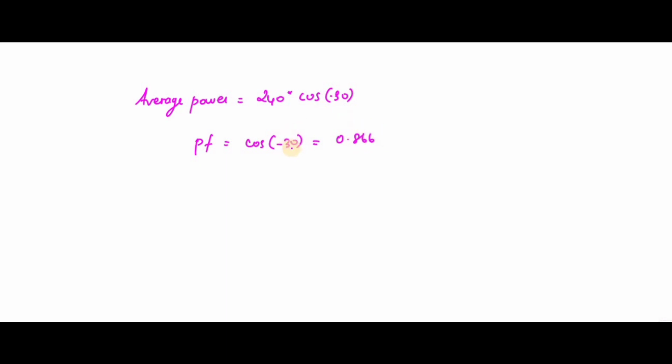Since it is minus, what is minus? Minus means it is leading, that is, current leads the voltage. So definitely they have used a capacitor as a load.